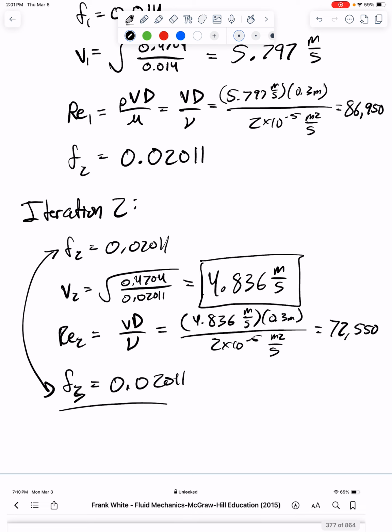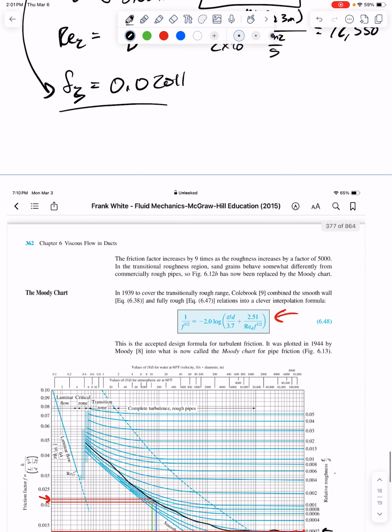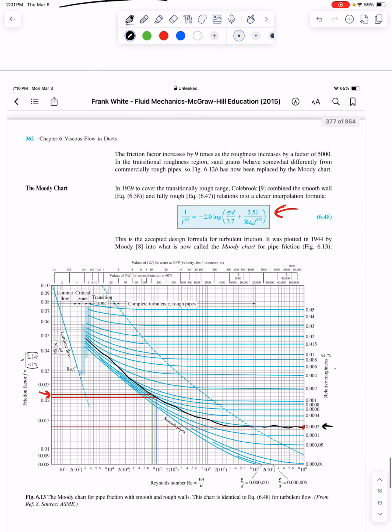Any questions on that process? For me, the main takeaway is the fact that friction factor is a function of flow characteristics and pipe characteristics. However, there's no real way to associate the two, besides this weird interpolation formula. Therefore, this Moody chart is able to showcase trends and characteristics and a way to interpret these values. And that's why the Moody chart is important, pi groups are important,